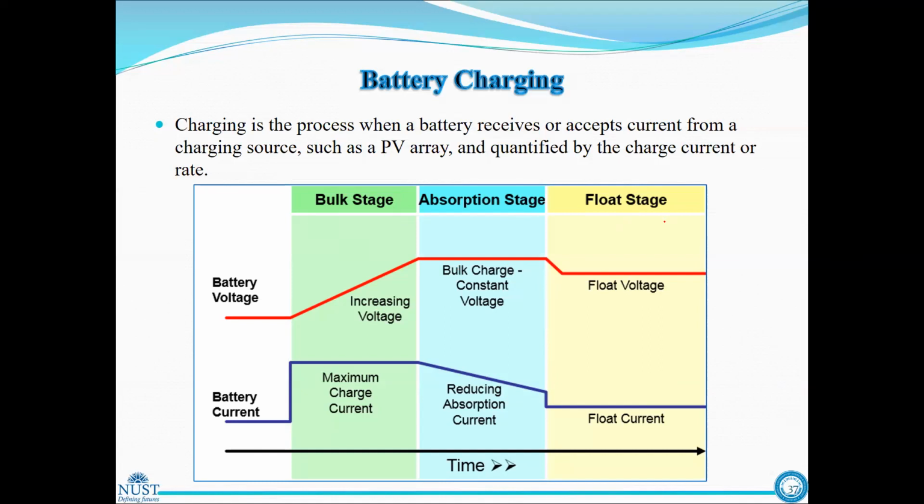So now if we leave the battery after float stage connected to the photovoltaic modules, the battery may heat up, because the temperature of the electrolyte, particularly in case of lead acid batteries, will be rising, and we may see some evaporation or loss of electrolyte.